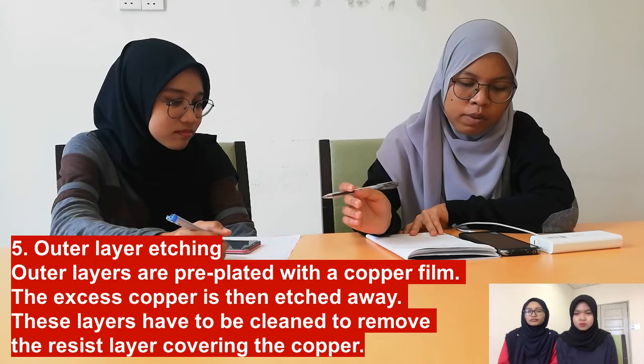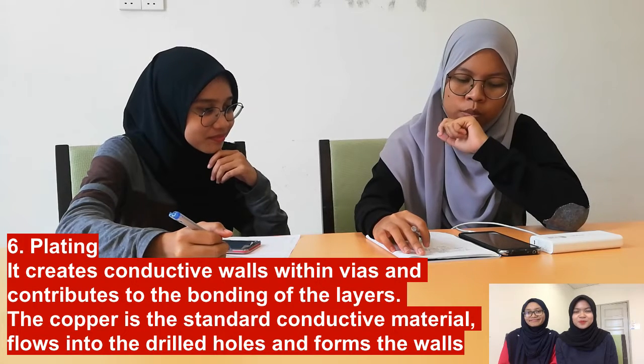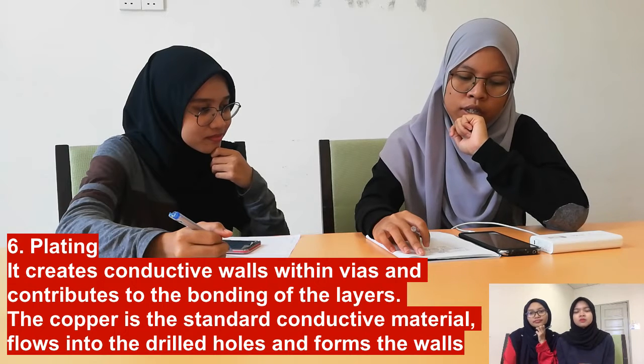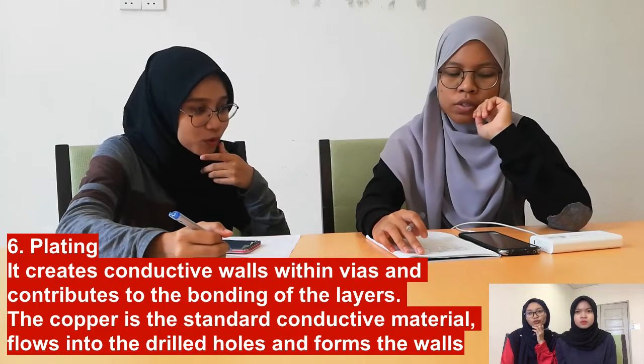The next step is plating. Plating serves two purposes. It creates conductive walls and wires and contributes to the bonding of the layers. The copper, which is the standard conductive material as we know, flows in the drilled hole and forms the walls.